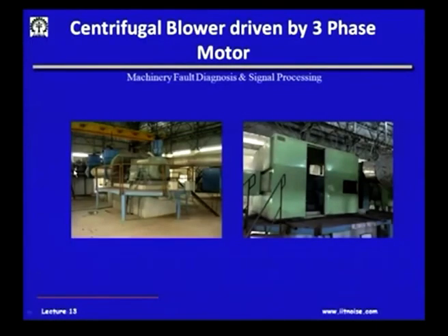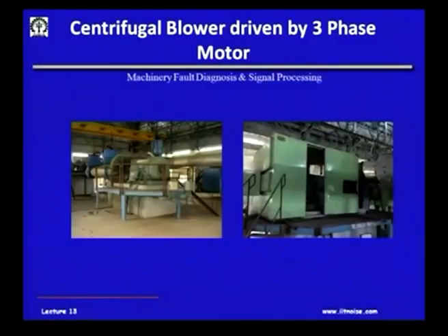Now, the reason I wanted to show you this is, this sometimes should not be confused as modulation, okay, because if you look at the response of a beating signal and a modulated signal, they look very similar in the time domain. But if you look at the frequency contents of these signals, they are quite different. In the amplitude modulated signals, I will see side bands FC plus minus FM, and also if I am interested to know FM, I can do the signal demodulation or do the envelope analysis.